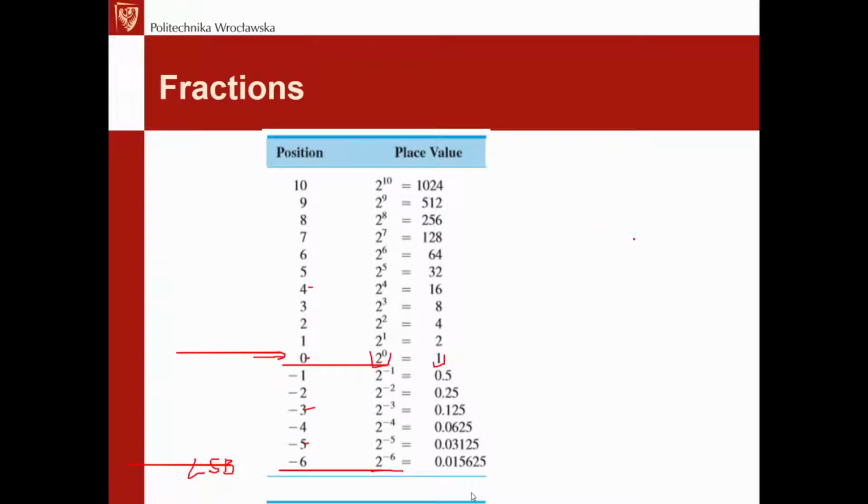In case of using 16-bit numbers, the fractionals make much more sense. Here, the decimal point is not in the middle, therefore we have 1/32 as the resolution of our number. Which is so-so resolution, but still we can move the decimal point, for example, one position up, and then we will have 1/256, for example, as the resolution, which is in many cases quite decent.